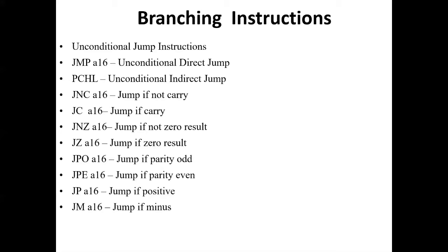And the last one is JM A16. JM is a mnemonic which stands for jump if minus. This instruction is used to jump to the address A16 provided in the instruction only if sign flag value is 1. If sign flag value is 0, program flow continues sequentially.